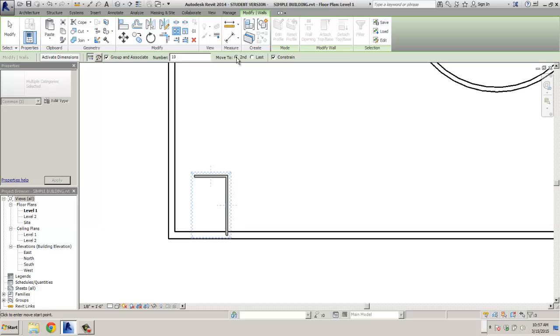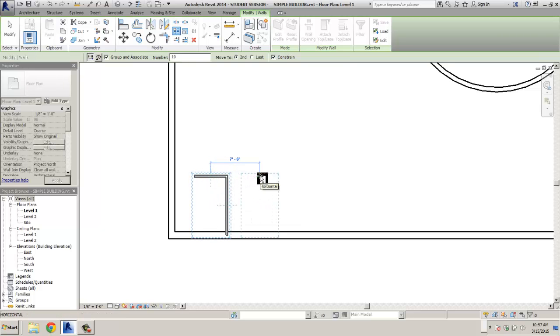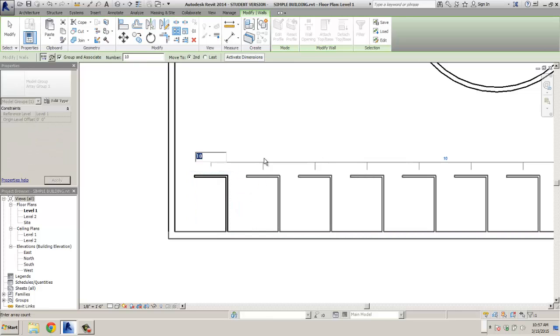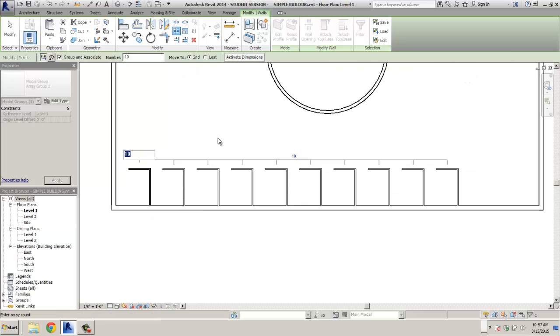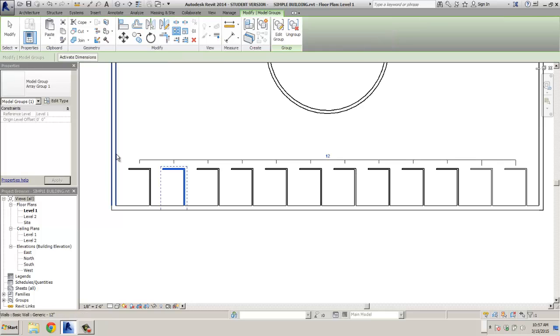We're going to select a point. Number 7 says in the drawing area select a point on the top horizontal cubicle. We're going to move at a distance of 8 feet, so key in 8 feet, and it creates 10 copies. Now it appears we can put more in there, so it says there's enough room available to add 2 more cubicles. Just change this number to 12 and it will add those extra cubicles in there for us.